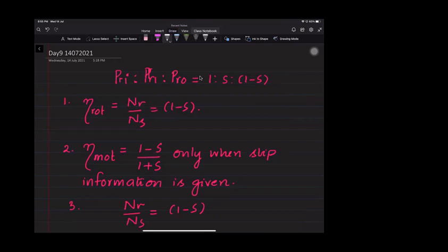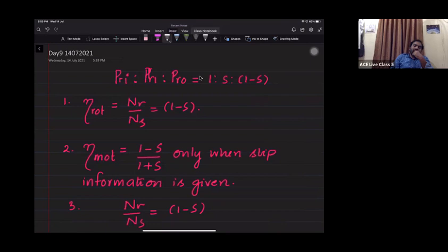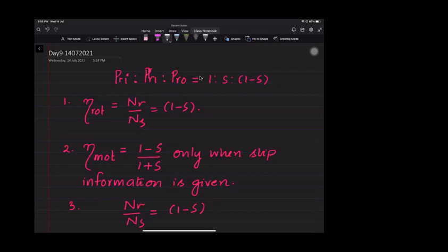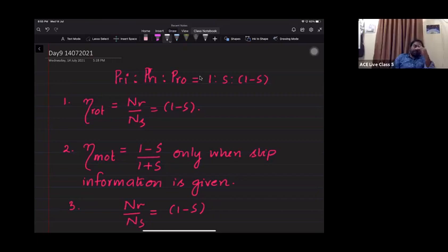Is it only for induction motors, or for any motor or machine? It is induction and synchronous, because the stators of both the machines will be more or less the same. You have to place it like that, but whenever you talk about the winding, it has to be always in electrical degrees. Understood. For another machine, how would it behave? It depends upon the number of poles.